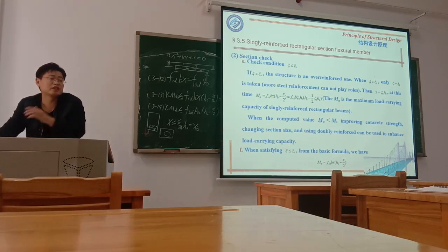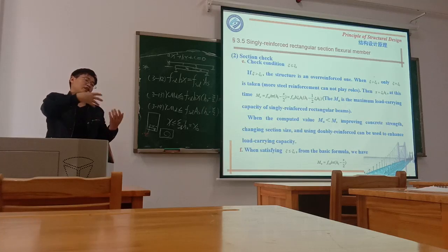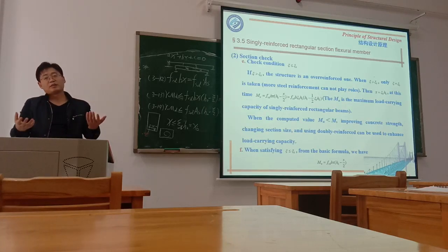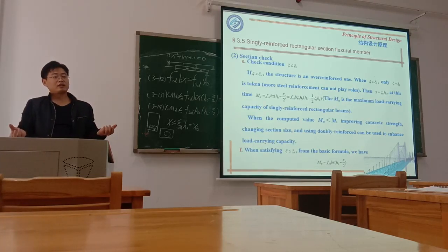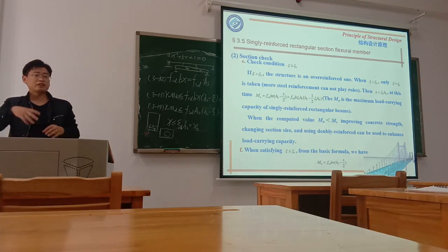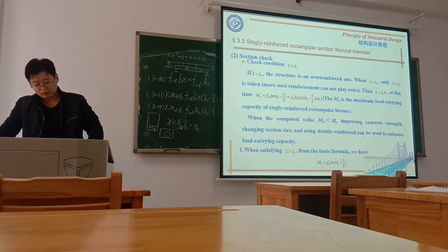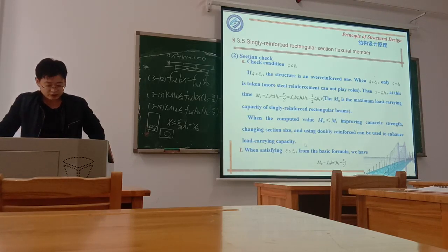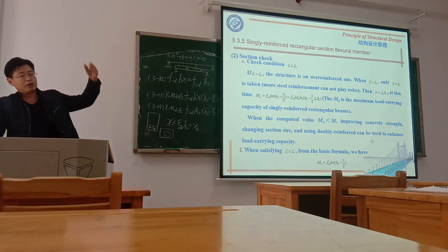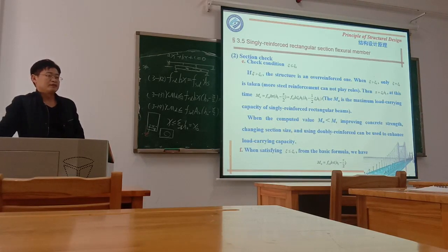If your resistive force is smaller than the load effect, then that means your design is not correct. It's not strong enough to resist the load. So you need to improve the concrete strength, change the size, or use double reinforcement to increase your load capacity.